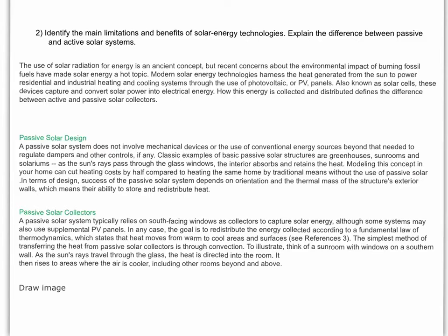So it's basically redesigning their houses to absorb energy into the house. Okay, so passively the energy comes in and it's redistributed. The heat gets redistributed and then it's stored in the walls or the concrete of the floors in the house. Now your designs, once again, use south-facing windows, although some systems may also use some PV panels.